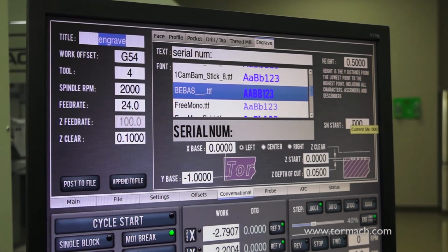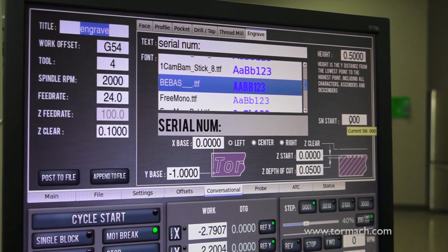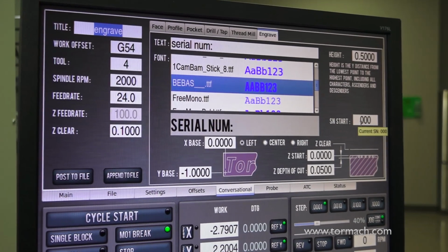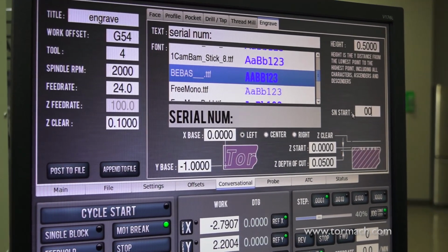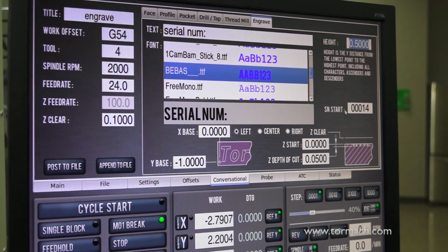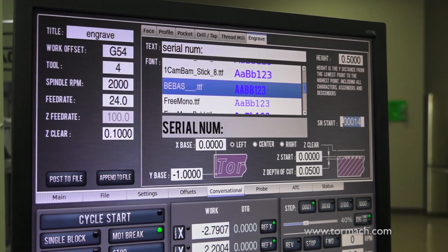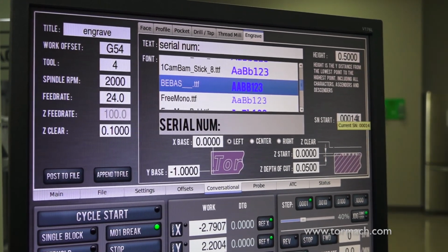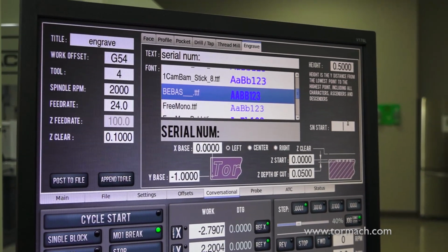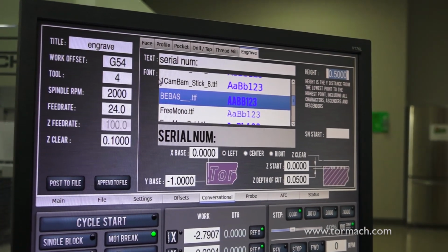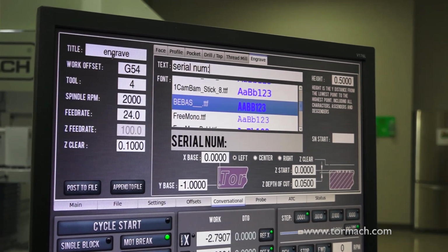Right now it's going to say the current serial number is 000, but if we ran this code a few times, and hovered over it, it would say current serial number is 011. If you want serial numbers with 5 digits, you could have it start at 14, for instance, right? But the number of leading zeros, the total number you want in here would be specified by that. And if you just leave it empty, no serial number gets appended at all, right? So that's the entirety of the conversational.